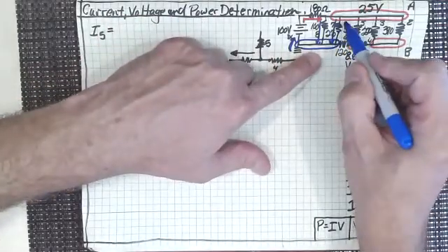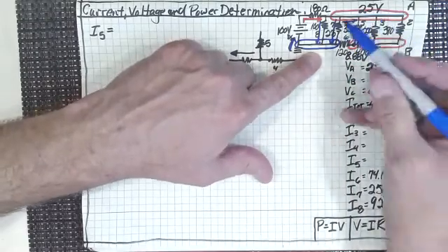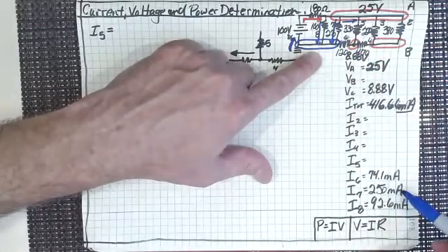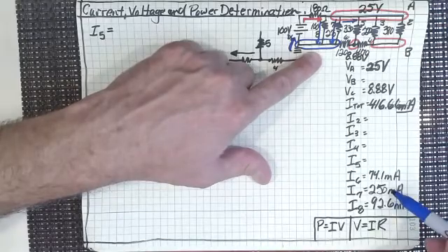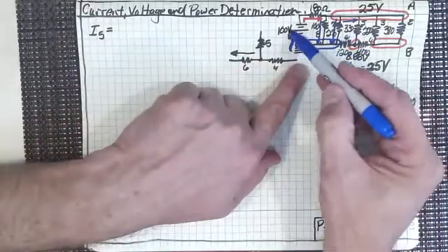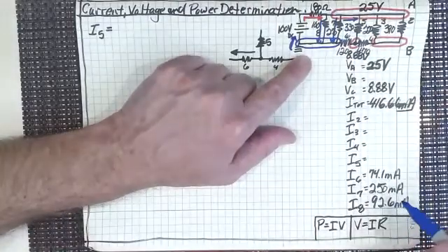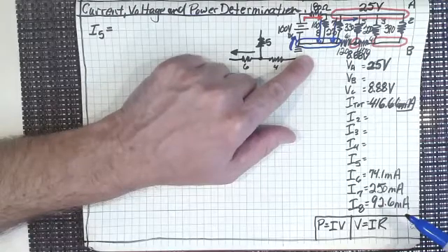So we know that what's going onwards from there is going to be less these two quantities, the 250 milliamps and the 92.6 milliamps that have come out and have gone back into the main river, if you want to think of it, river of current flow. Not electron flow, though. Electron flow, of course, is opposite to current flow.